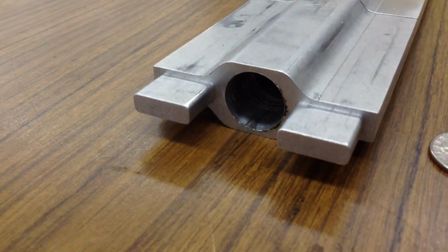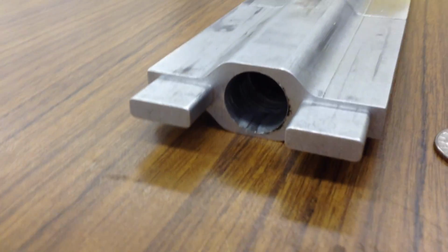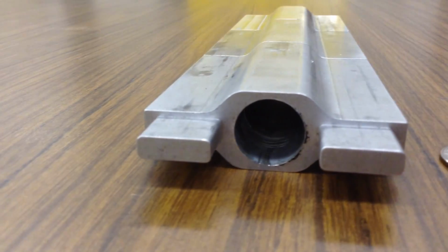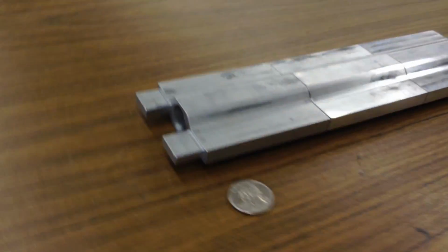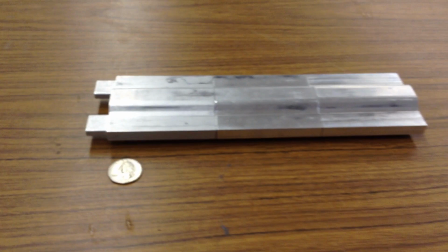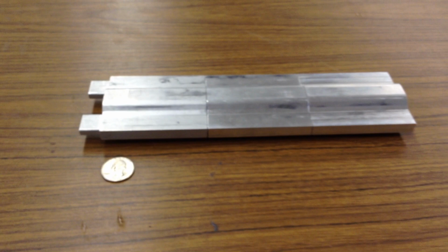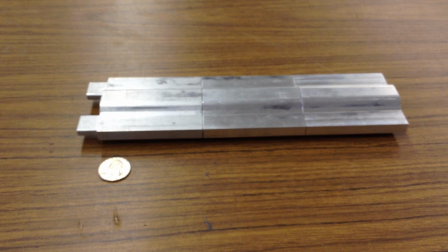On the other end, you see the tongue extensions of each spar piece that feed into the subsequent spar piece. As you can see, not all spar pieces are broached to accept the spline shaft. Only the ones on the ends and in the middle require the broaching.